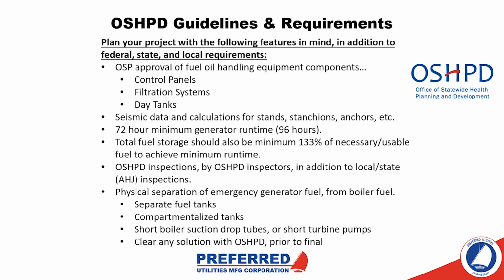72-hour minimum generator runtime, I believe that's pushed out to 96 hours soon, in a number of years. It's approaching, and I can get more specifics on that. If anybody's interested, just email me. Total fuel storage should be a minimum of 133% of the necessary or usable fuel in the system to achieve the minimum runtime.